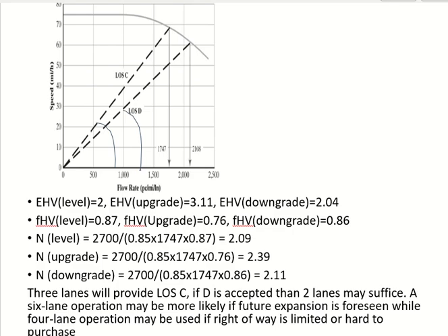Now you can see these lines are plotted. Now I have to plot the line. You will go from the origin, so you have the point. Now you need what? The angle. If you are taking the angle from the speed axis, this is what I did here. Is it written? Not written. Fine, I'll make it easier for you. You need the angle of the line, which should be equal to density, right? Density is flow upon speed. What is tangent theta?